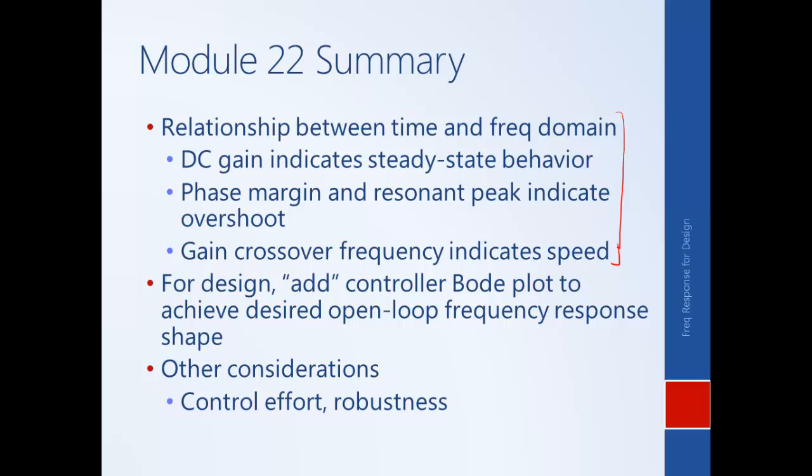We also discussed how to design controllers, and we saw that we used the open-loop Bode plot because it allows us to just add the controller Bode plot to the plant Bode plot. So it's very easy to anticipate the shape of controller we need to reshape the open-loop frequency response. And we also discussed at a qualitative level some more advanced considerations, things like control effort and robustness.